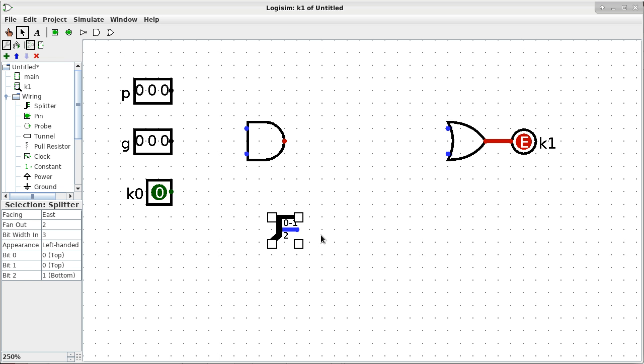If you want your design to look extra clean, you can have a fan out of 1, because we really only need 1 bit out of the 3, so you don't need the other split ends. On the other hand, if you say, I don't want to mess with that, I'm just going to get all 3 bits, and I'll just leave some of these split ends unconnected, that's fine too. That's your choice. Is that okay? So I'm going to use this particular approach just to emphasize which bit I'm using.